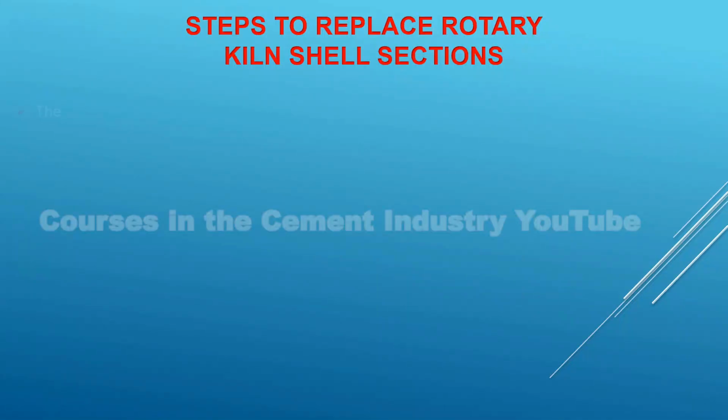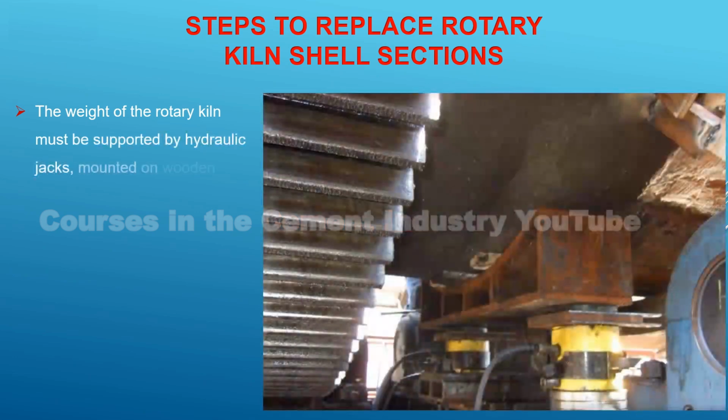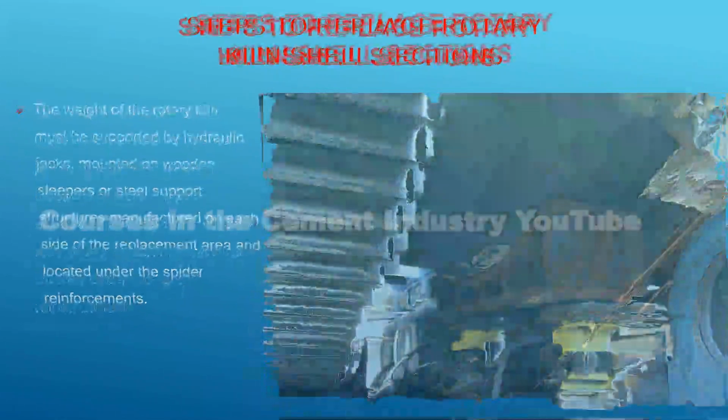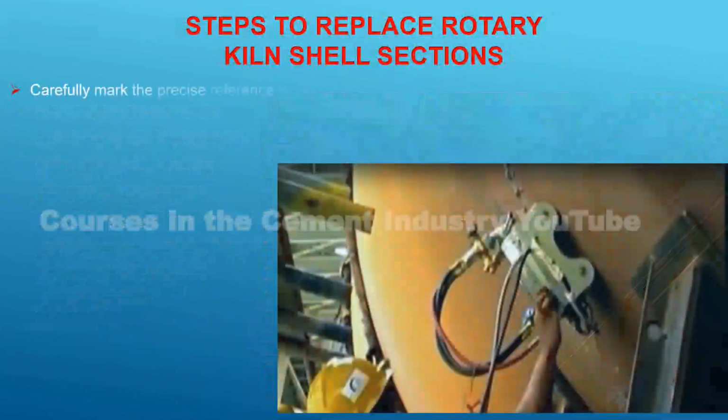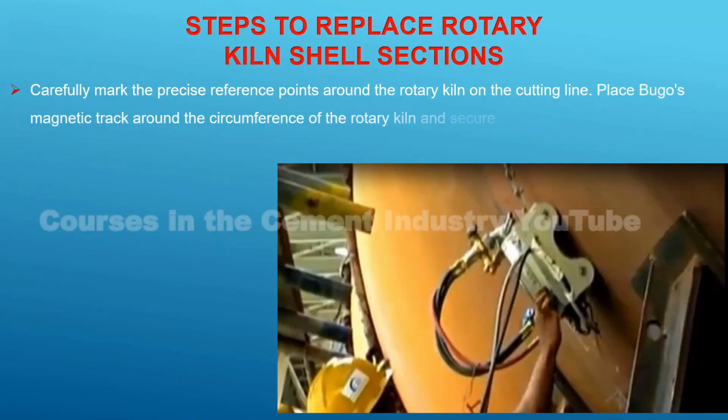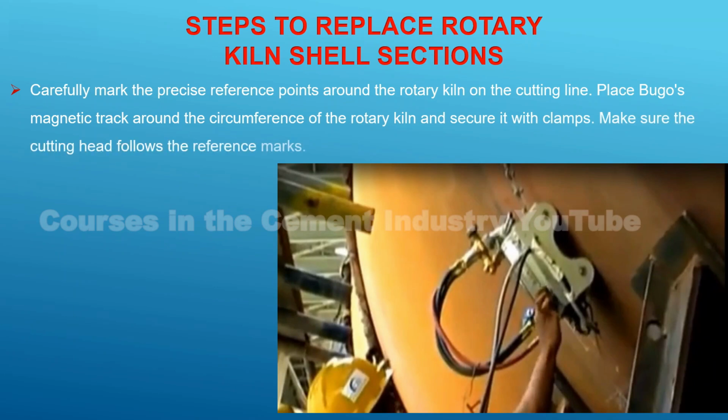Step 6. The weight of the rotary kiln must be supported by hydraulic jacks mounted on wooden sleepers, or steel support structures manufactured on each side of the replacement area, and located under the spider reinforcements. Step 7. Carefully mark the precise reference points around the rotary kiln on the cutting line. Place Bugo's magnetic track around the circumference of the rotary kiln, and secure it with clamps. Make sure the cutting head follows the reference marks.